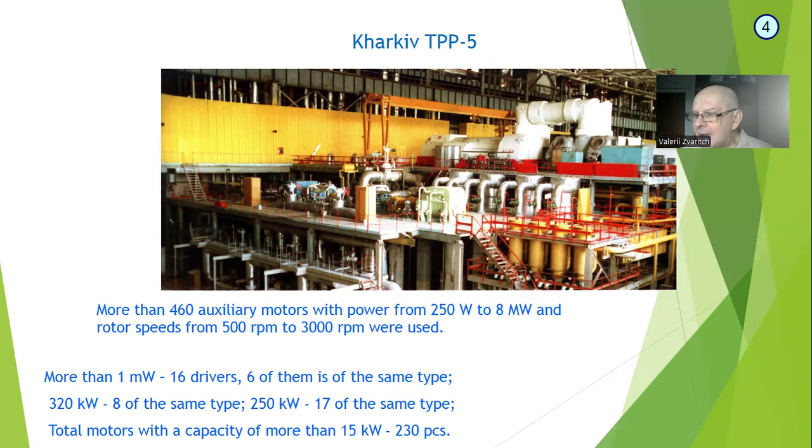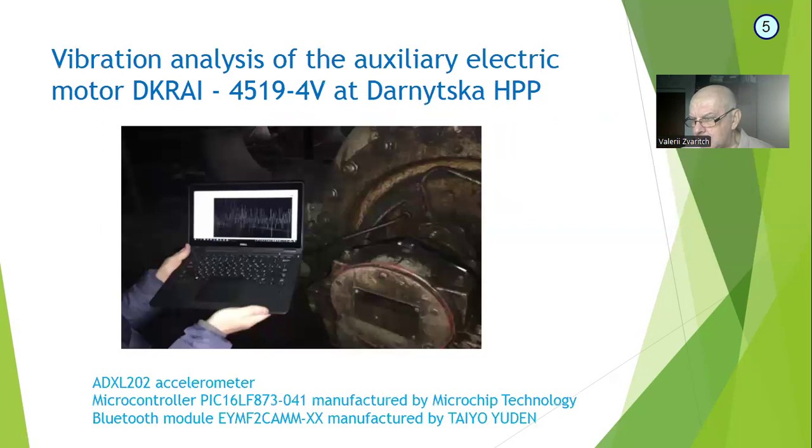A prototype of a wireless diagnostic system was developed at the Institute of Electrodynamics, Ukrainian National Academy of Sciences. The analog signal measured at the units of the electrical machines under diagnosis at the output of the sensor is a duty cycle modulated signal. The ADXL202 accelerometer manufactured by Analog Devices was used as the primary sensor.